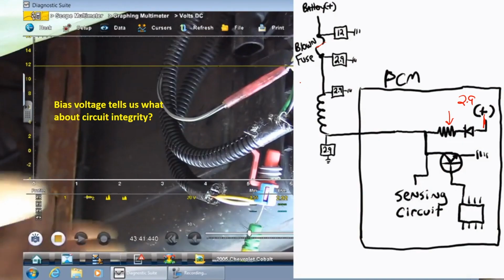If the fuse is good, what do we have? 12 volts here, and that 12 volts, driver's off. That's important, no ground. That voltage runs through the coil. It's looking for a ground. There isn't one. We have 12 volts on this side. Continues on. Is the sensing circuit a path? It is not. The computer's reading 12 volts on the sensing circuit. That's why it's there. It's used for diagnostic purposes. You can look at outputs on the scan tool and know if they're commanded on or off, or if there's opens or shorts. That's where that's coming from.